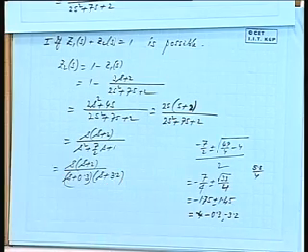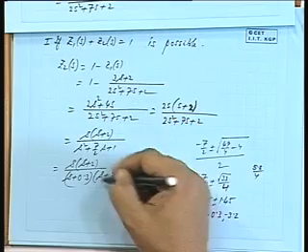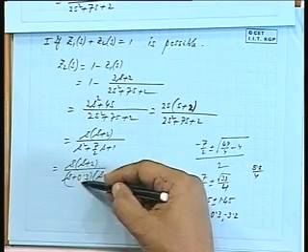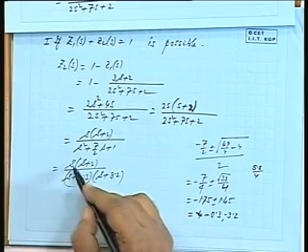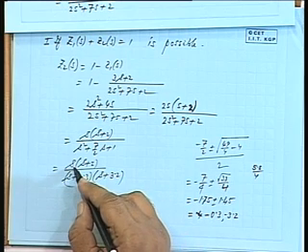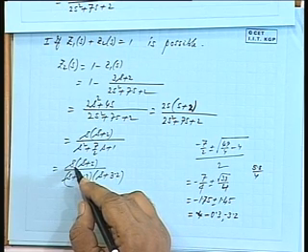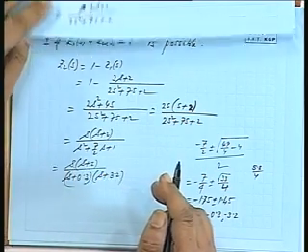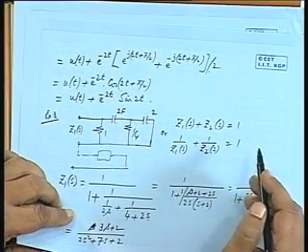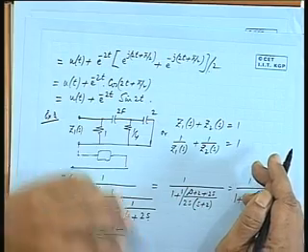Does it sound like any of your known RL or RC network functions? Does this appear to be any of those RC or RL networks? Are the poles and zeros alternately coming? Yes. 0, pole, 0, pole. So it will be either RL or RC. Now 0 is the closest to the origin, so it will be an RL network. Intuitively you can guess it has to be RL because it is an RC network, and finally it will be only real, so the C part has to be compensated by L, is it not?